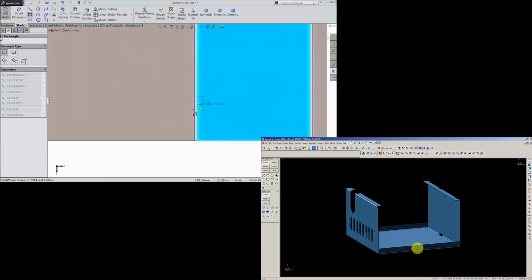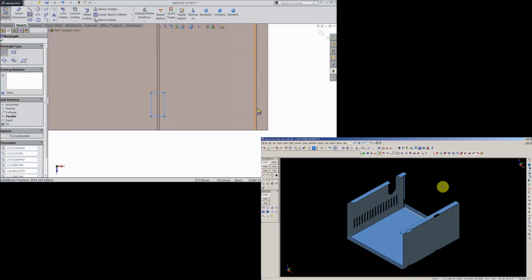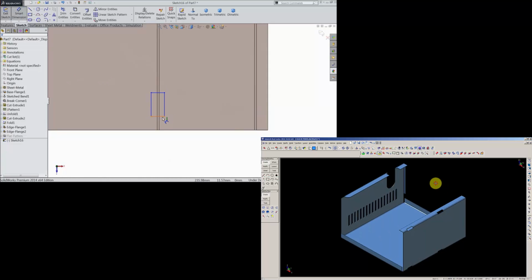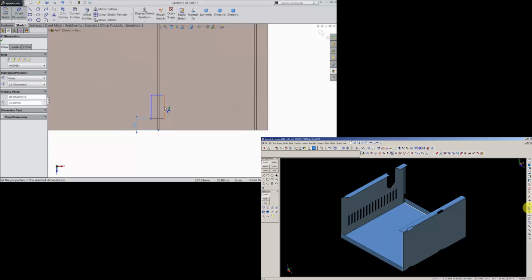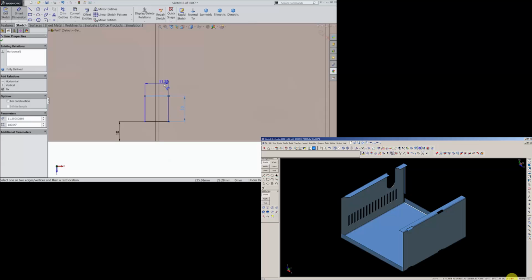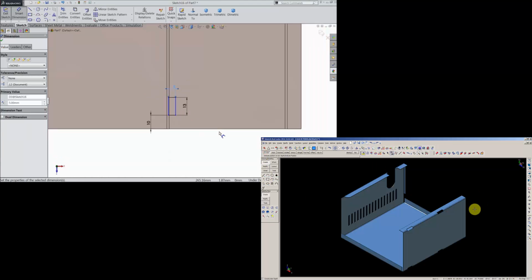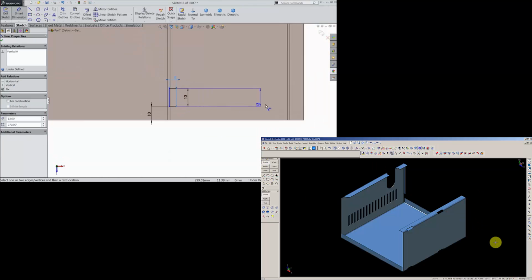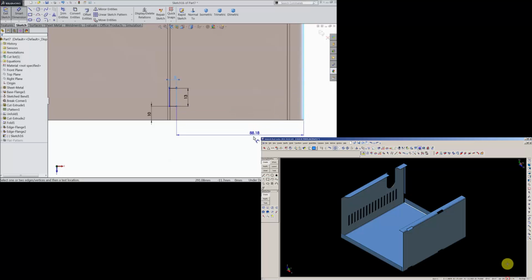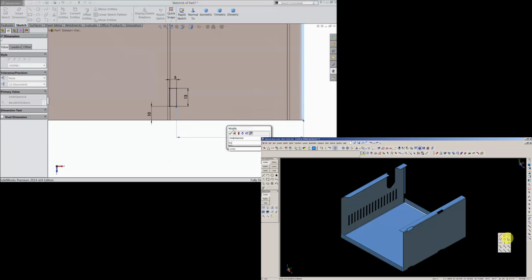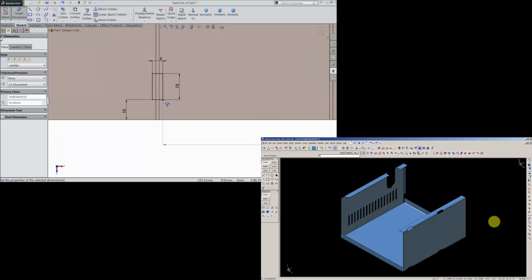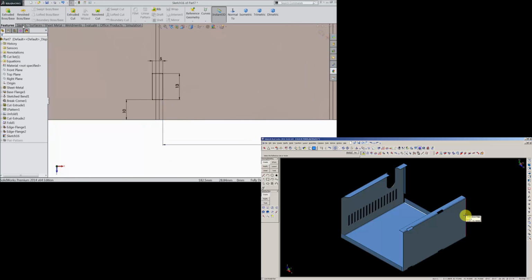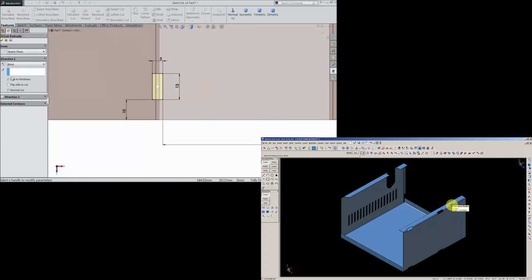Select corner rectangle. Now define this rectangle 10 mm from outside. Keep the length 13 mm and this width 5 mm, and distance from outside 91 mm. See. Okay. And select extruded cut and make sure link to thickness. Okay.